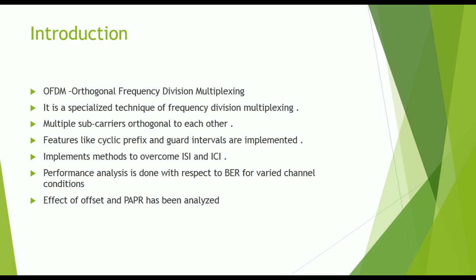So, what is OFDM? OFDM is a multi-carrier system that has gained its importance because of its ability to reduce failure rate, fading effects, and inter-symbol interference that a single carrier system suffers from. Orthogonality of the subcarriers is the key element that makes it so sought after because it ensures that the subcarriers are harmonics. As a result, when these subcarriers add up, they do not cause interference. It helps achieve a high bit rate, immunity to multipath, spectral efficiency,